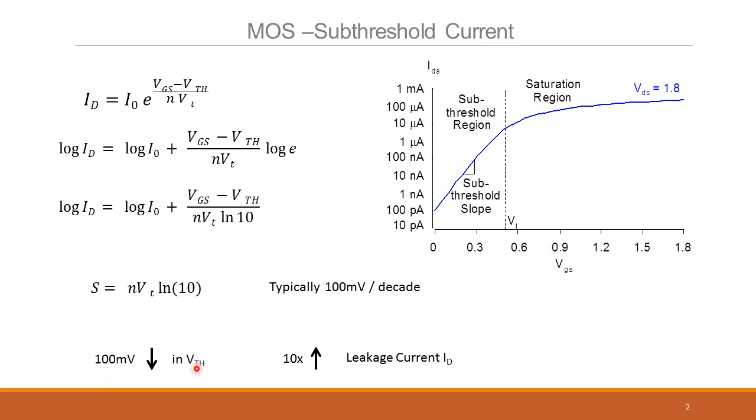In deep submicron technologies, as the process voltages are reduced, you cannot scale VTH by a large amount. Let's say the 5 volt process, we had 0.35 microns at 5 volt process, dropped down to 1.8. Now core transistors are 0.9 or even 0.8 volt supply voltages. But VTH, if you take a look, has scaled from 350 to 400 millivolts down to about 200 millivolts.